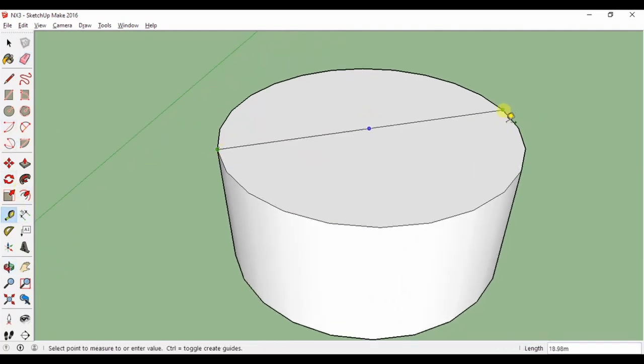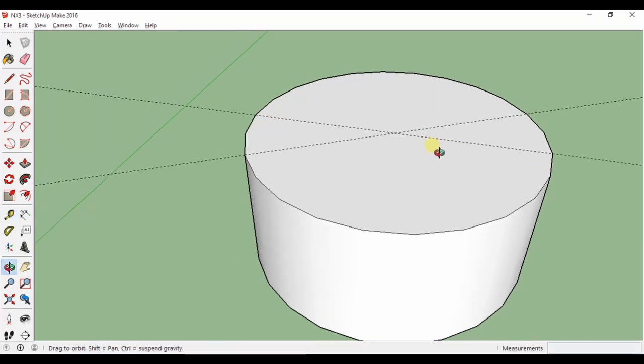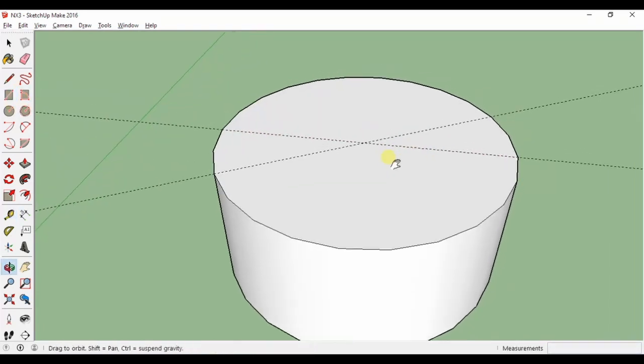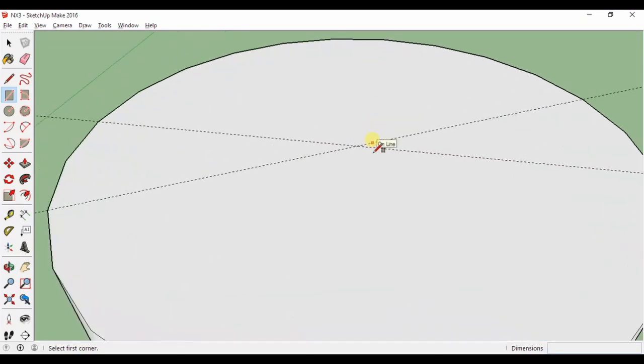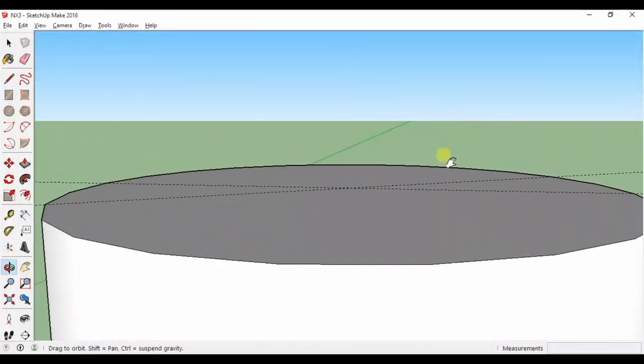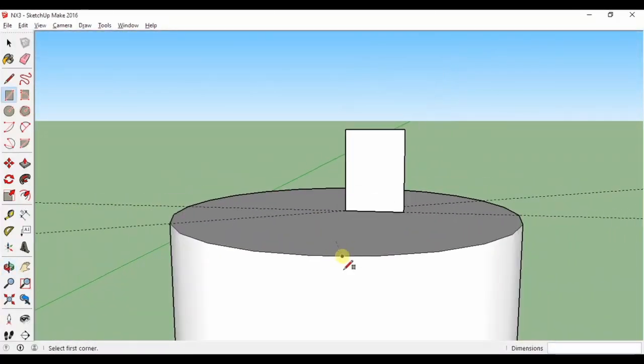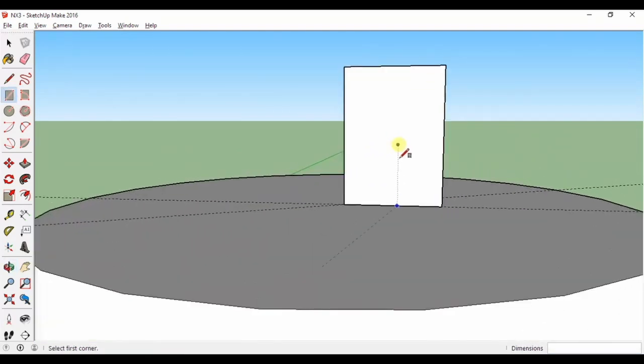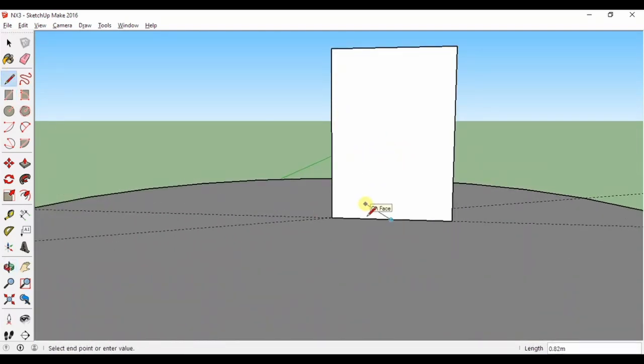I now move on to drawing the rotating mirror. This will only be a rough representation. For this I'm going to use the Follow Me tool as well as rectangle and line. Firstly, I'll draw the shape. This is best done by drawing a vertical rectangle first, making sure to angle my camera low down so SketchUp can intuit what I'm doing. Using the line tool, I carve out the shape I'd like to be lathed.